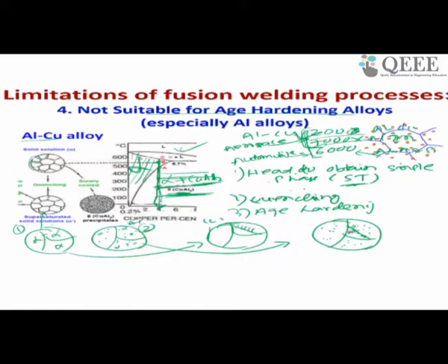And to overcome this motion, when can it move further? Suppose this is the size of the particle. Only when the dislocation breaks this particle into two pieces can the dislocation move. So for breaking that particle into two pieces, you need to apply high stress. So the strength of the material will be high.